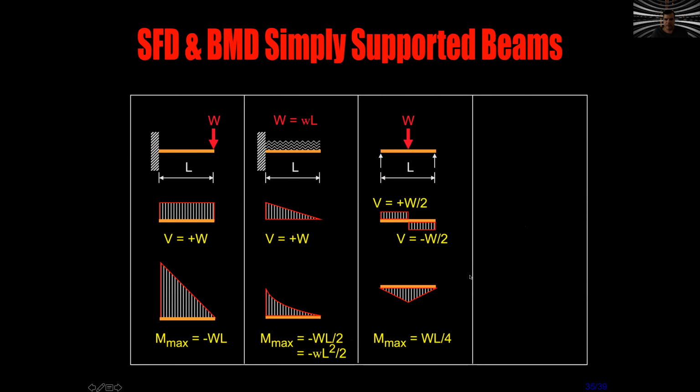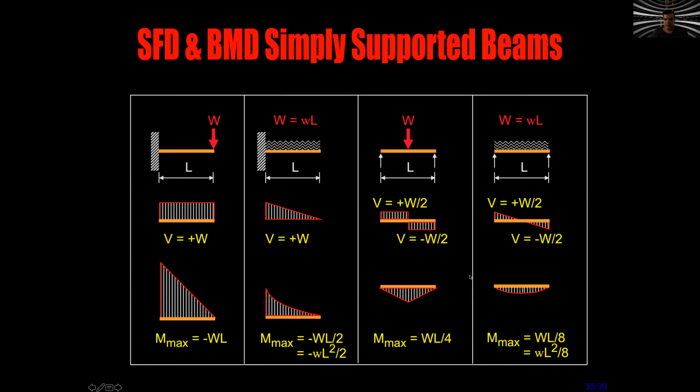And in beams that are in cantilever, the same happens. Look, the moment is maximum at the ends here. Sorry, the shear is maximum in case number 3 at the ends, and passes through 0 in the center of this W. Very important thing, because when the shear is 0, the moment is maximum.